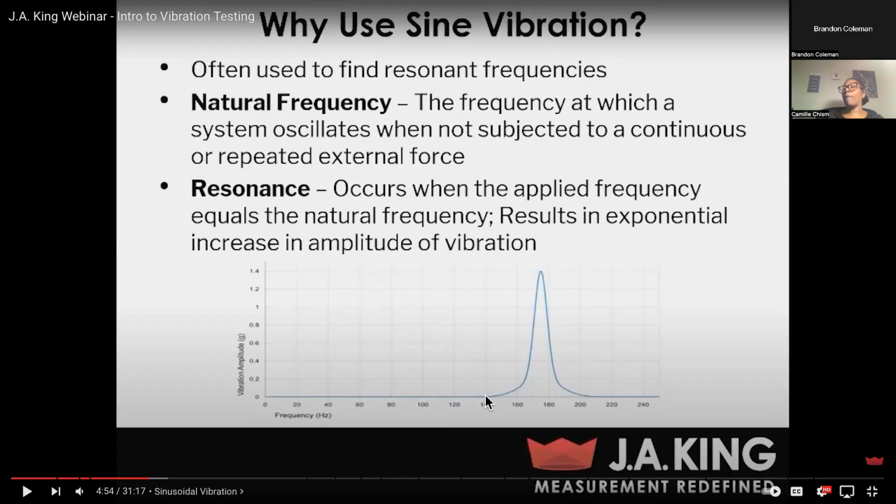It seems really low, but when that truck, if it's on a truck and it hits that same frequency and it just amplifies this, all of a sudden you see this big event, you see this big bump in the amplitude, meaning that part, whatever that natural frequency is, if it matches the truck, it will amplify. And that is an opportunity to damage a part.